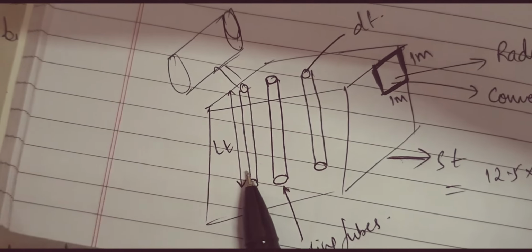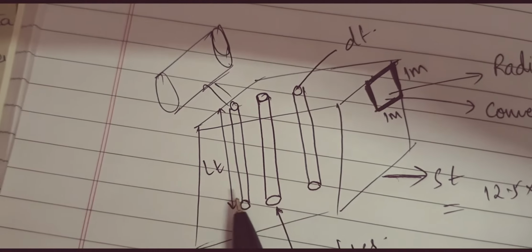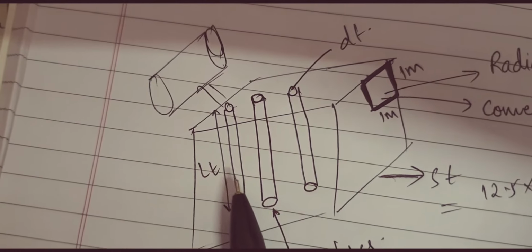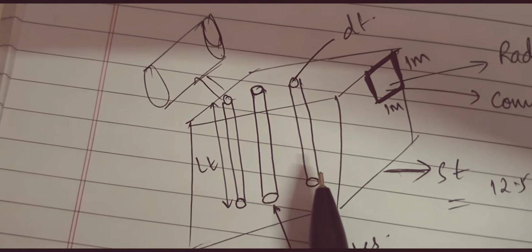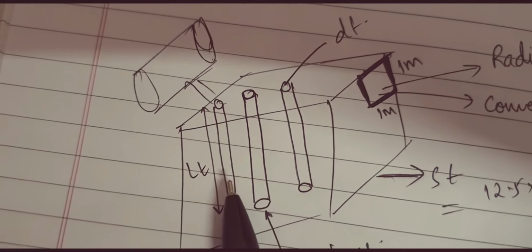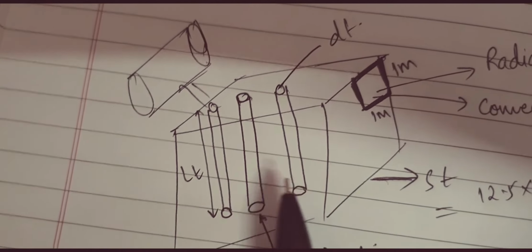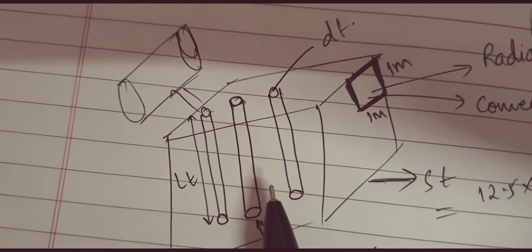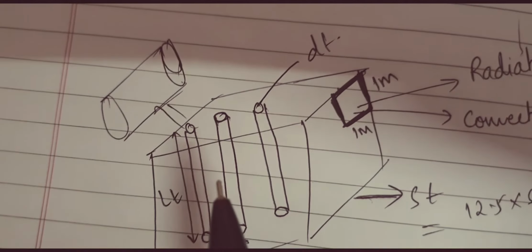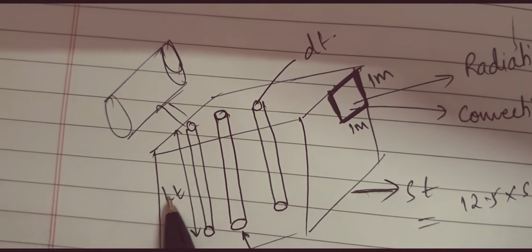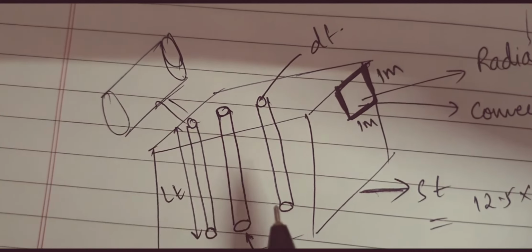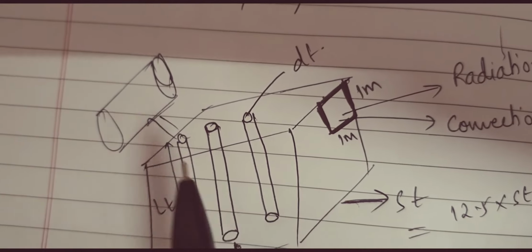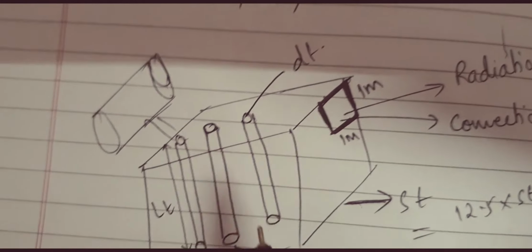As we can see, we have added some cooling tubes here, and I said to you that after adding cooling tubes to the transformer, its convection process improves by 35%. It means now these cooling tubes are dissipating heat at 8.8 watts per meter square per degree Celsius to the surrounding. Therefore, the total loss occurring at cooling tubes can be given as the total surface area of these cooling tubes into 8.8 into rise in temperature.